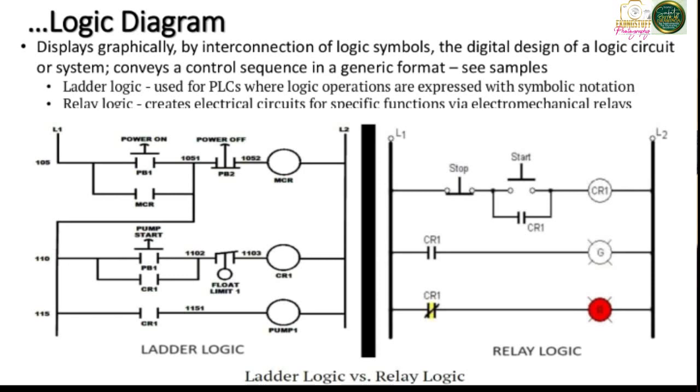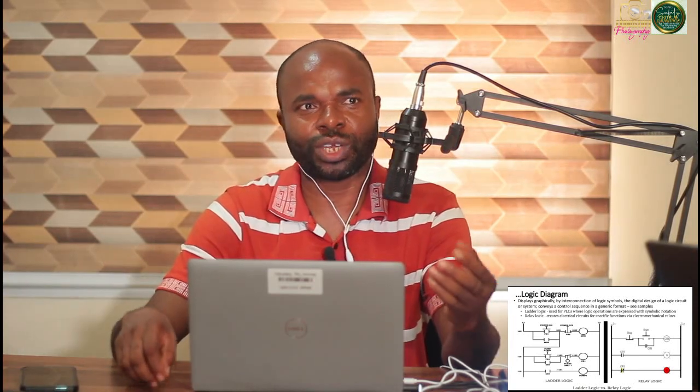Another type of drawing that can also be very valuable and plays a key role in maintaining safety on a typical facility is a logic diagram. This typically displays the interconnections. You typically will see symbols that are used to represent the interconnection between different loops. And like the name implies, logic. I mean, picture a typical PLC that says, okay, if this happens, initiate this. If this happens, initiate this.